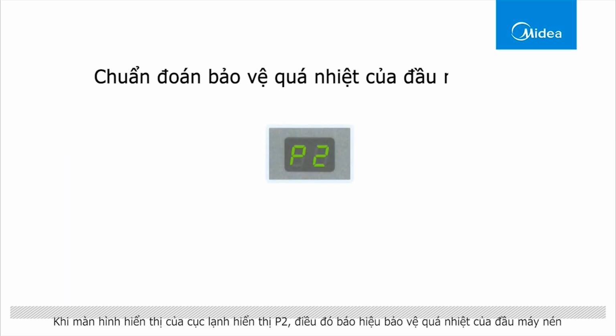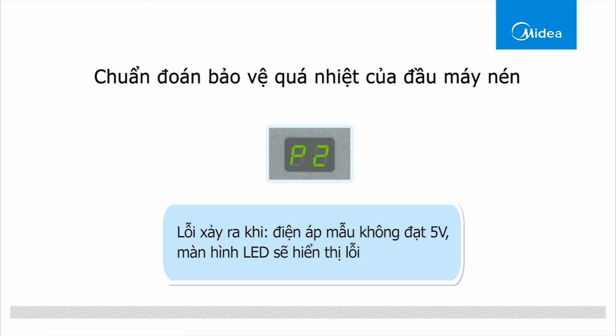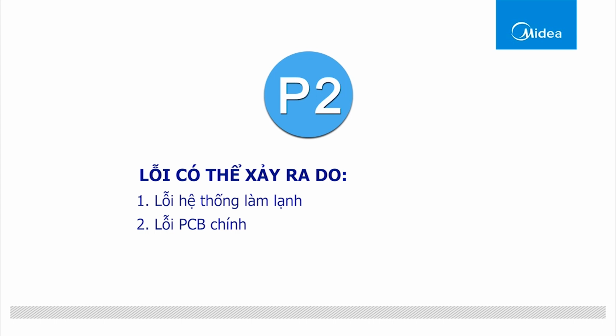When the indoor unit displays P2, that indicates over temperature protection of the compressor's top. Malfunction decision conditions: If the sampling voltage is not 5 volts, the LED will display the failure. The failure could be caused by: 1. The refrigeration system error, 2. The main PCB error.